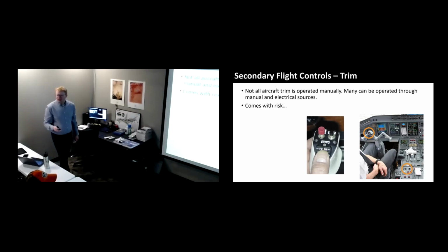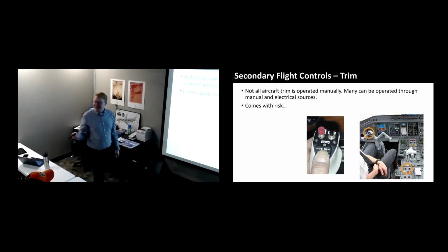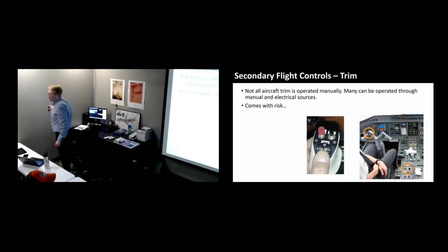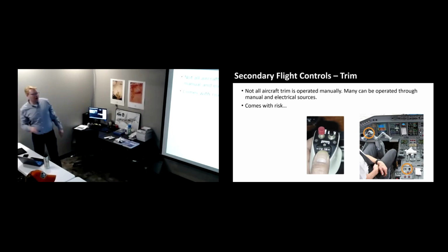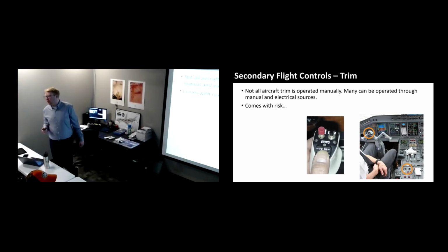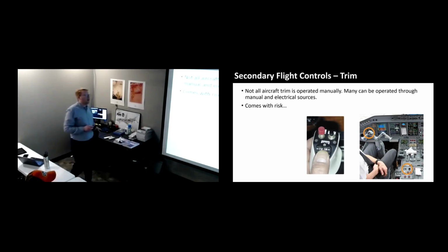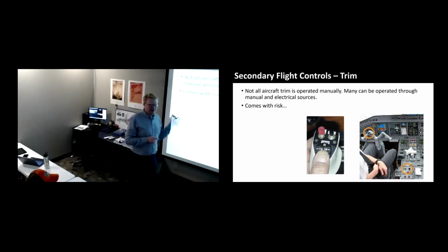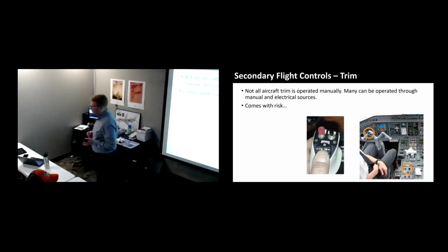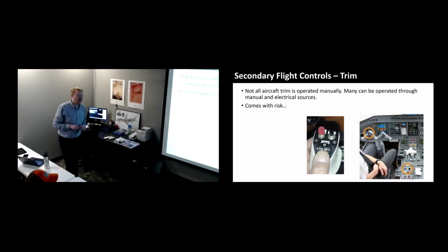Stop it. Pull a breaker, disconnect the system, whatever that specific airplane setup is, depends on how that airplane runs its trim setup. They're all going to be some form of electrical setup, so usually it's an electrical system. It also could be a trim system circuit breaker or a button in the cockpit you can press to disconnect them. Sometimes they're not always pilot inputs. If you move into the larger airplanes, you'll look at augmented inputs with trim from a computer to assist the pilot flying the airplane to keep feel.